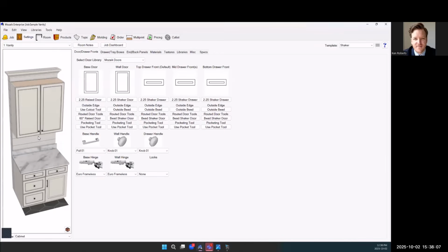We have a question from Derek, and that's going to be, what type of V-bit is recommended for inside bevel shaker for the cleanest result? Insert versus solid carbide, 2 to 3 flutes? I always used a 2-flute insert. They're a great tool, easy to replace the blades. They're consistent. My old shop, we ran thousands of MDF doors with insert tools and had a great experience with